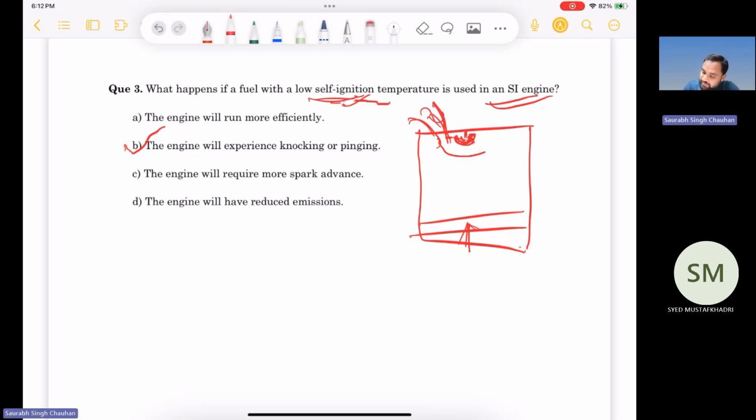So the flame will be traveling towards the unburned region. Okay, so it is traveling in the forward direction. Whatever mixture is behind this flame has already burnt. Because of combustion of this mixture, the temperature and pressure inside this chamber will become quite high, and